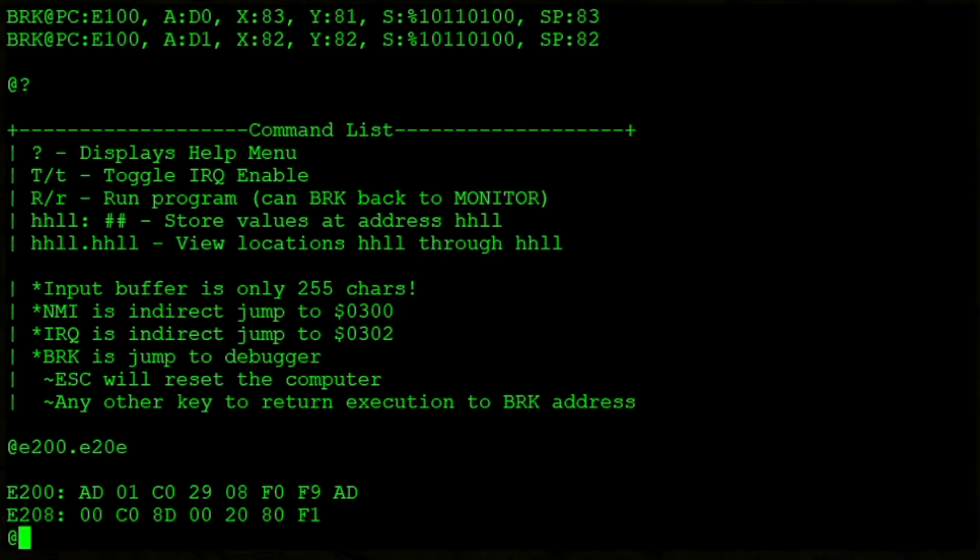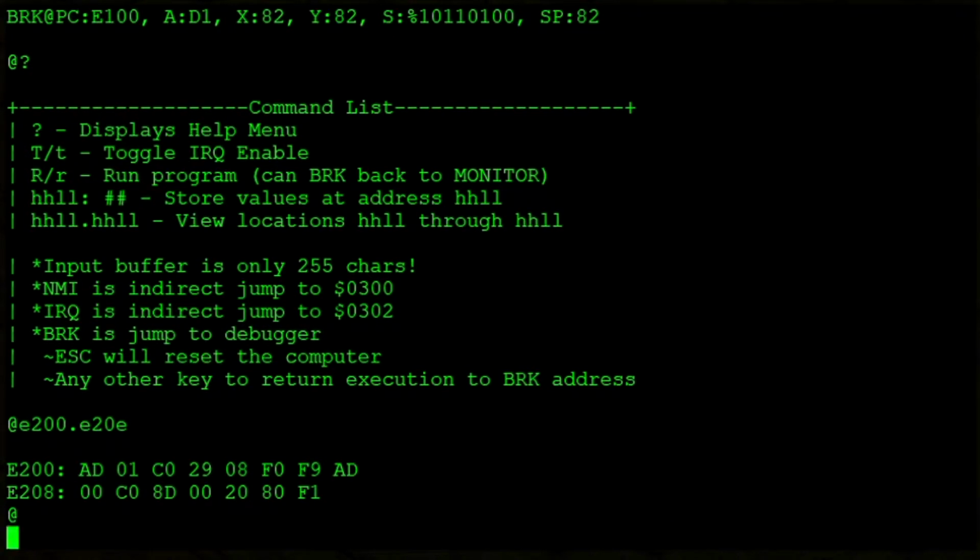This is the 65C02 version of it. Because it's from WDC and it's the more modern CMOS version of the processor, I can use instructions like the branch always that will speed things up a little bit. Sometimes in here you'll see a push X or things like that, and that's just because I'm running the newer version of the processor. So the code here is not 100% compatible with the original NMOS version of the processor.